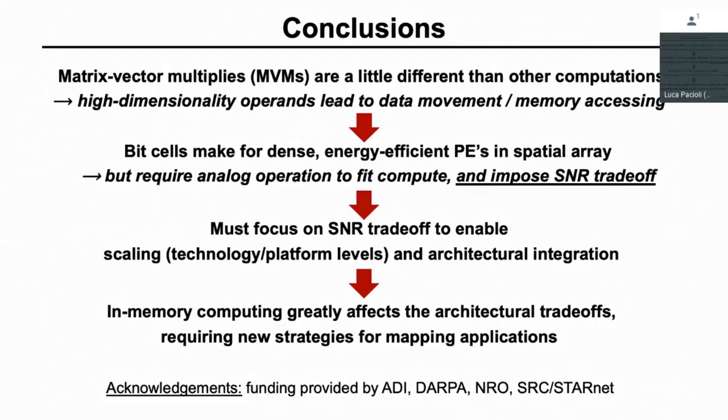And then the other question here is, for these different kinds of neural networks, you have highly varying sizes. I have some amount of hardware, and of course I'm going to virtualize that eventually. But for now, there's some amount of hardware, and there is some utilization loss. So we've tried this across a bunch of different neural network applications. I'm happy to describe the details of the corner cases here, but as long as you can put all of your weight parameters on chip, and by the way, as you're moving to 4-bit precision, this is actually pretty viable to do, you start to think about the size of networks that you have. If you can do that, you can get very close to full utilization.